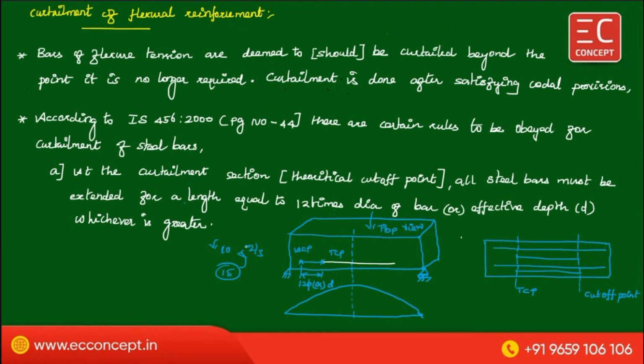So the condition is, you don't want to terminate if the external shear force coming on this section is more than 2/3 of the shear capacity. For example, the external force is 10. This shall not be more than 2/3 of the shear capacity of this section.